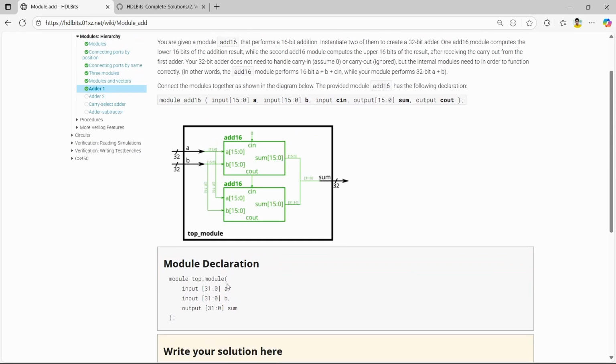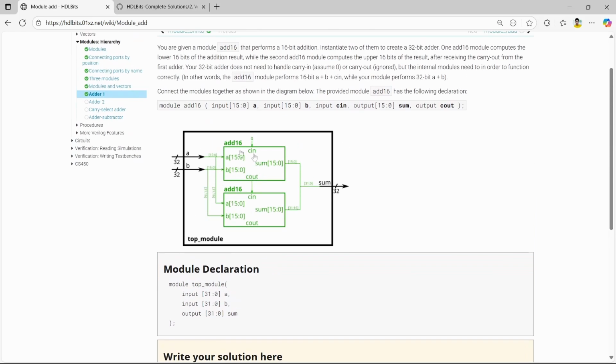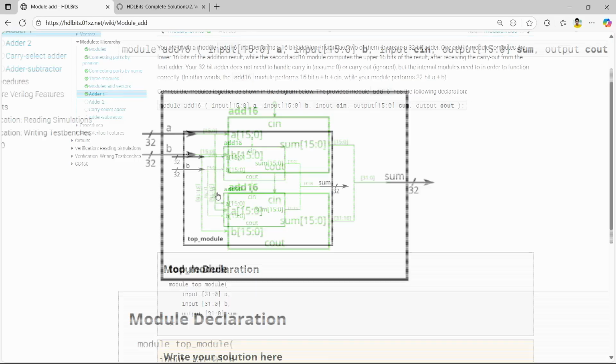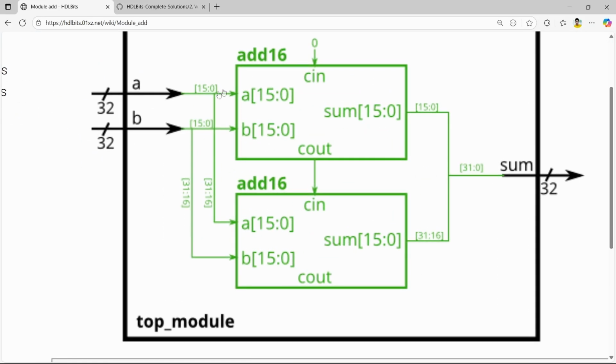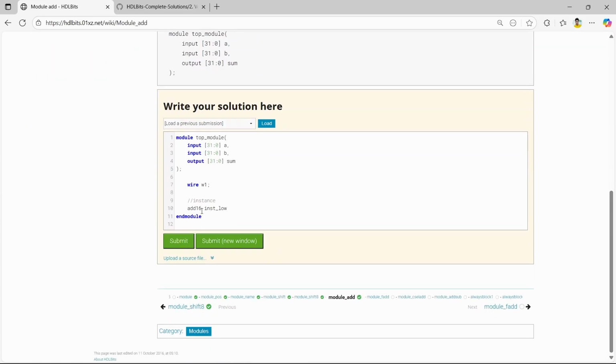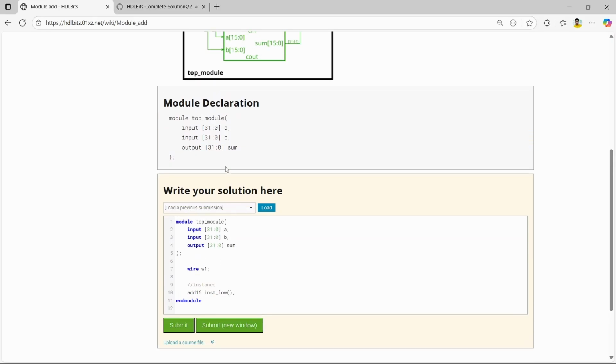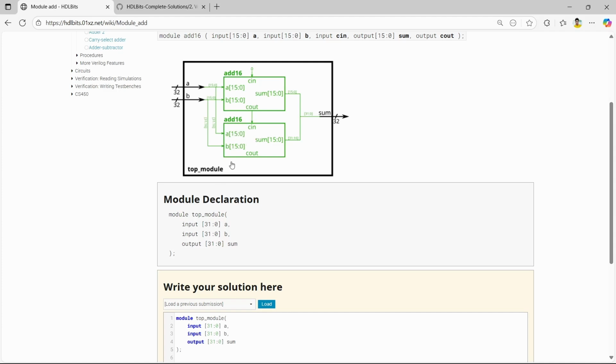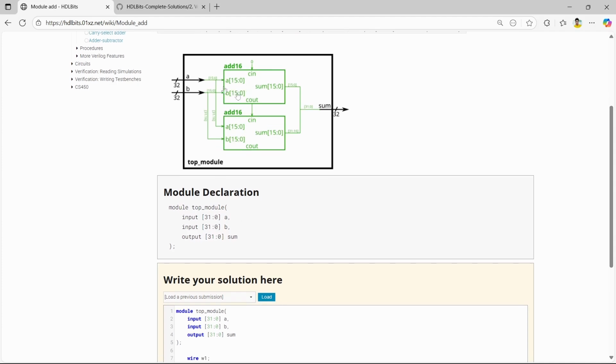The lower bits are being treated here, and the upper bits are treated in the other instance. So it's stripping down to zero lower bits, 31 down to 16. The name should make sense when you declare it, so when someone is debugging it's easy, or even when you read your code again, you don't need to think so much. So this is the inst_low, 15 down to 0.